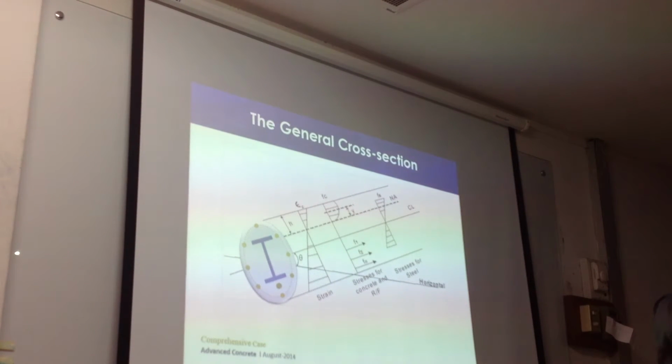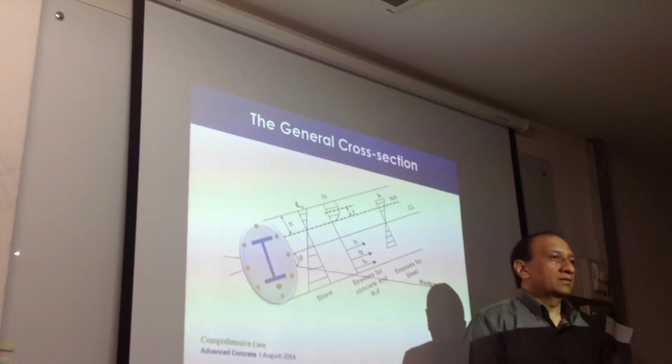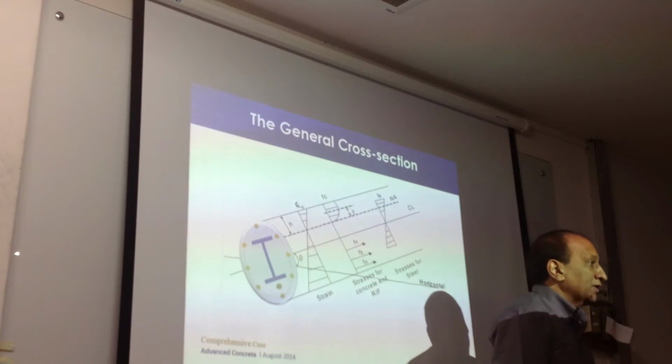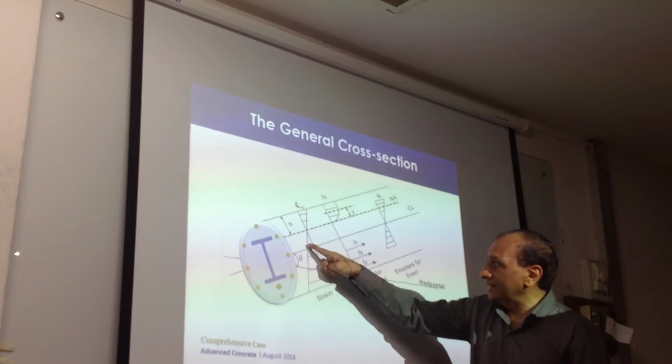Any strain, it is bending. We don't know the strain, doesn't matter. All we're saying is there is a strain. And the diagram, for now let's assume that plane sections remain plane. Okay? And based on that strain, we can calculate strain at every level.